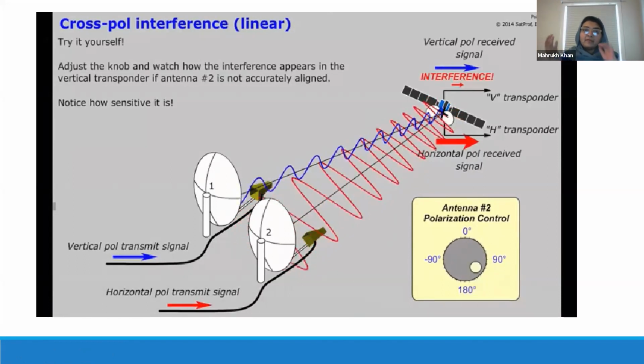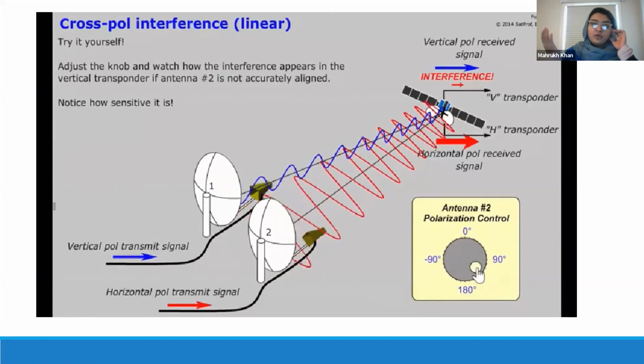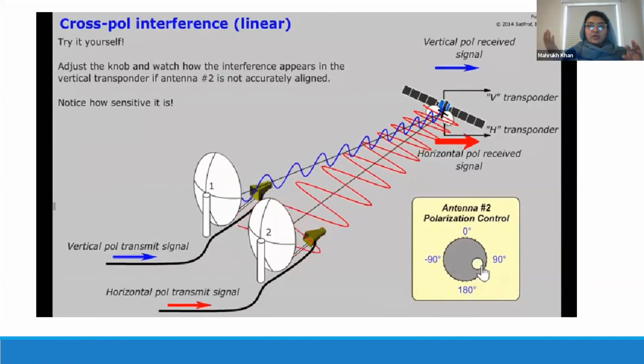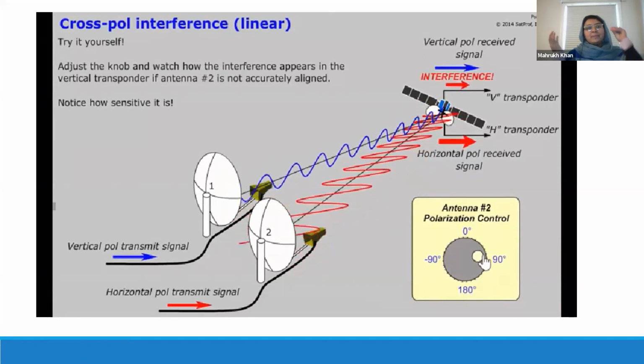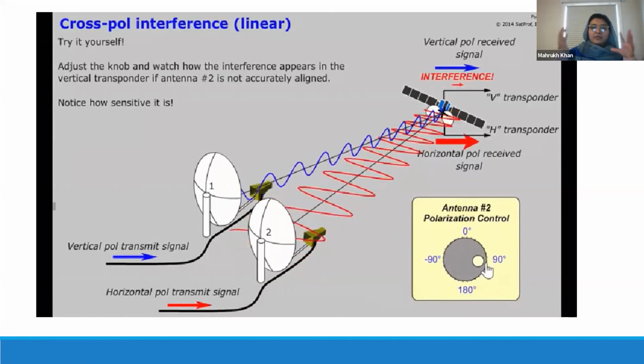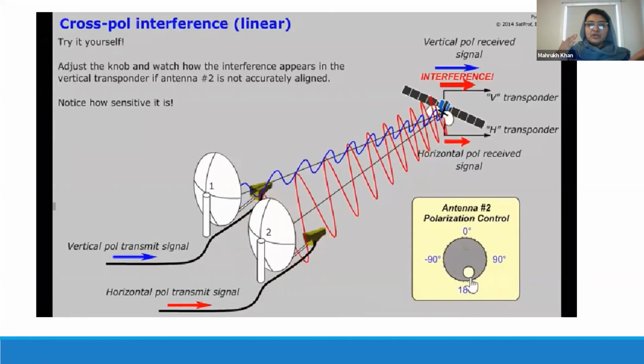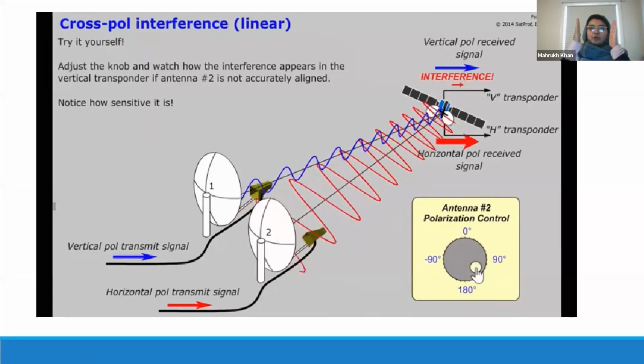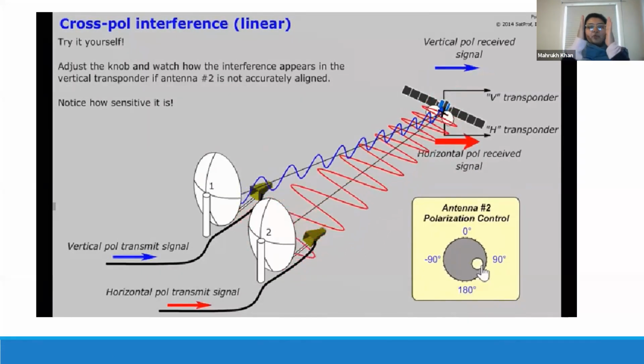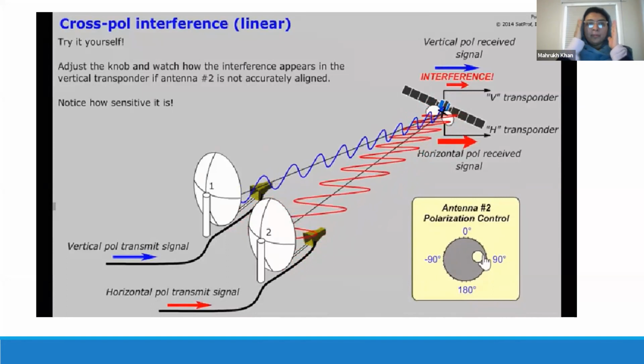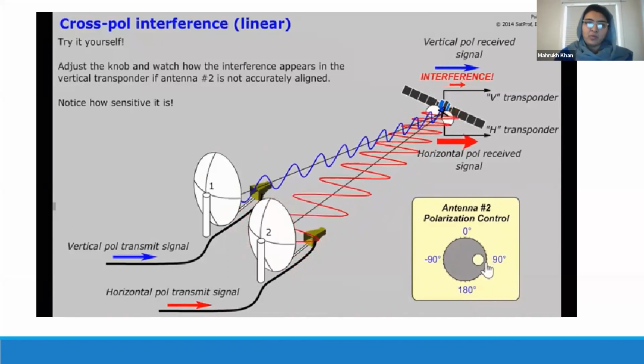Cross pole is some unwanted polarization that you do not want to receive. You want this cross pole to be minimum. But if you set your polarization control to receive the vertically polarized wave, then they both will be copoles. Copoles means the wanted signal that you want to receive.